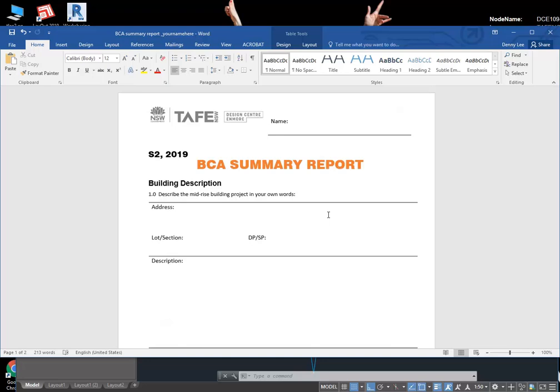So it can be glass from a certain height? Yeah, just check it up. I think it's 450 or whatever. It's not that high. Well, I'll do that so they still get the light, because the whole point is that the light comes through to there. Privacy would be a problem as well, because they can look down from this unit into there. So I'd make them 1800 high, so they at least get light above that height, but they can't look down into the courtyard of the unit below. Yeah, then it solves it.